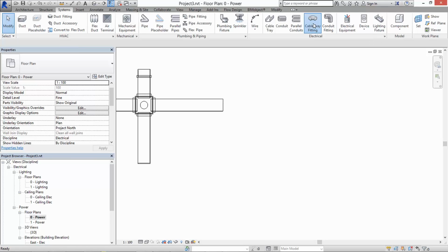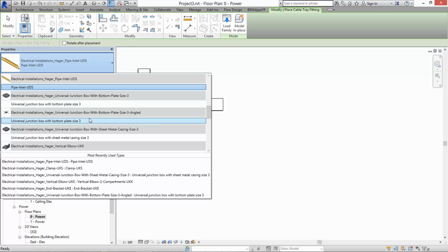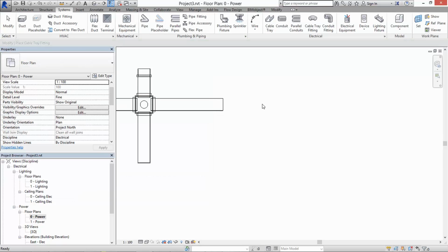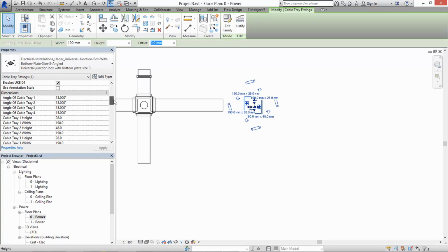To connect a straight cable tray with an angled one, please select the junction box type Angled. If you tooltip or hover over the instance properties of the angle settings, you can view the minimum and maximum constraints of the cable trays. This junction box type allows you to change the angle of the cable trays on all 4 sides.